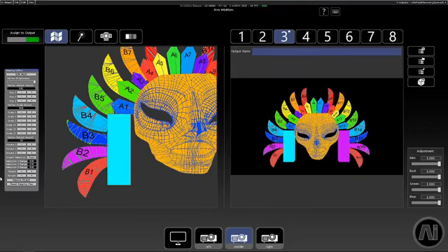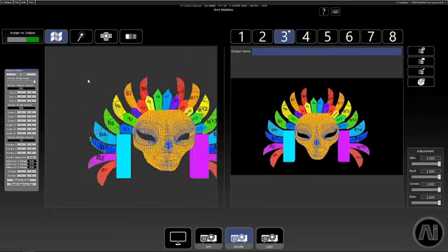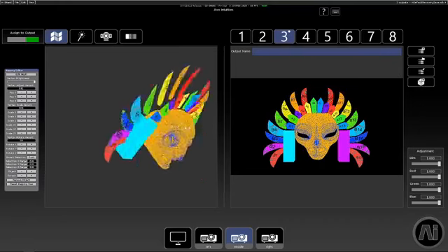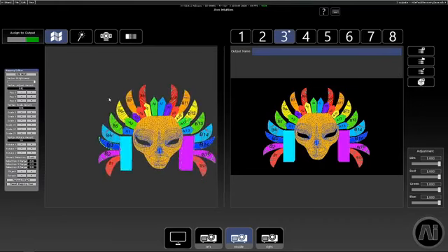So we've got 2 modes on this mapping editor, and at the top of it is this button that says Edit Mesh. So the first mode is when the button is not pressed and the writing shows in black. So in this mode I can easily move around, I can manipulate, all that kind of stuff, but I can't actually select any components. So if I give that button a quick press, now I can actually drag select and select specific components of my model. There we go. We can see they've just turned pink because they're now selected.